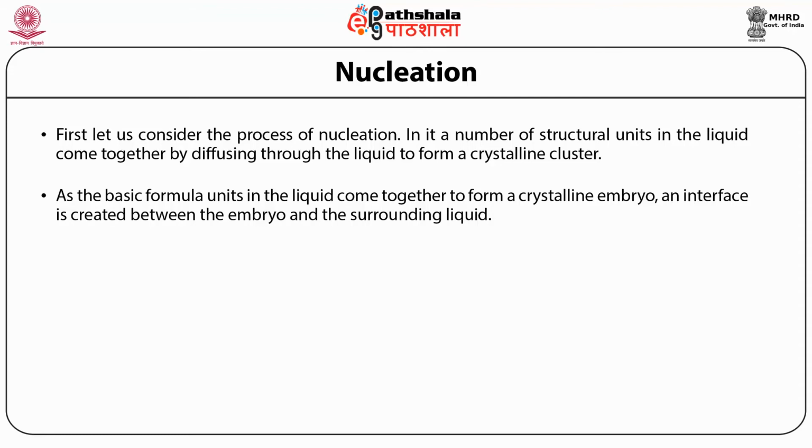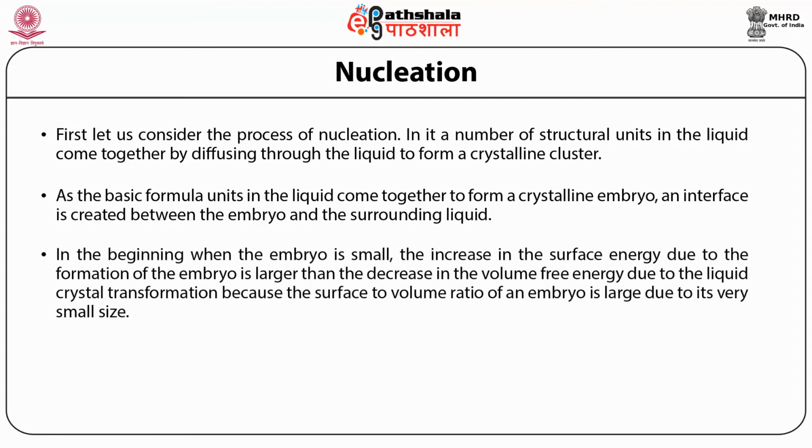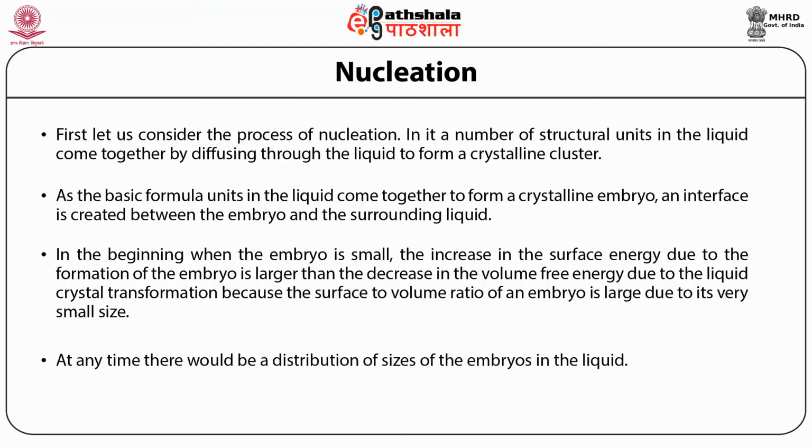This interface has a certain surface energy. In the beginning, when the embryo is small, the surface to volume ratio of an embryo is large due to its very small size, so the increase in surface energy dominates as the liquid changes into crystal. The embryo formation therefore causes an increase in energy, and the embryo tends to dissolve back. At any time, there would be a distribution of sizes of the embryo in the liquid.